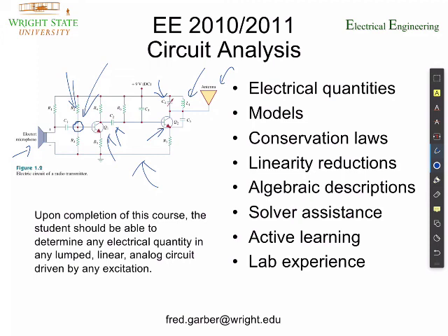So the same is true in circuits. In fact, that little realization that if I add up all the flow out of a region, it has to equal 0, is what's called Kirchhoff's current law, which is the key to unlocking the analysis of virtually every circuit on the planet.